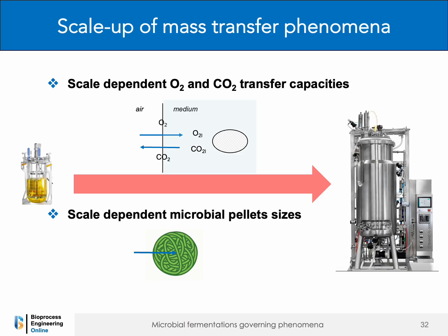This challenge is further amplified in fermentations involving filamentous microorganisms. Due to scale-dependent flow and mixing patterns, pellet size distributions may change, affecting internal diffusion of nutrients and oxygen within the pellets, and leading to varying degrees of mass transfer limitation across scales.